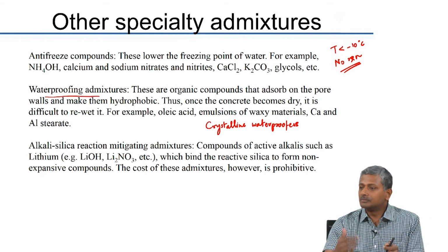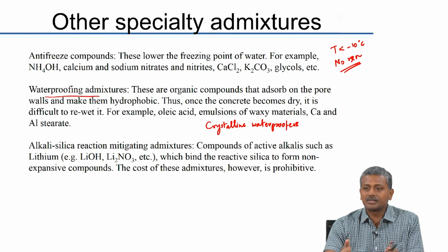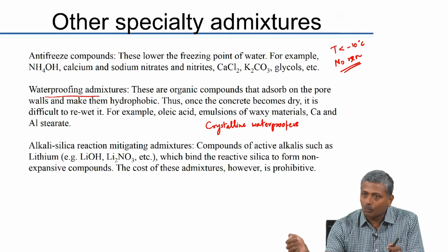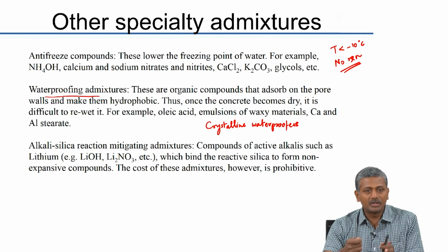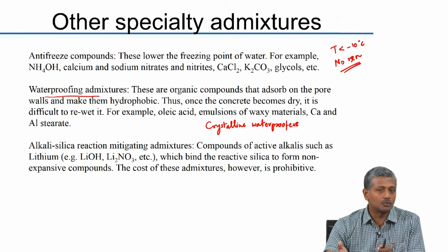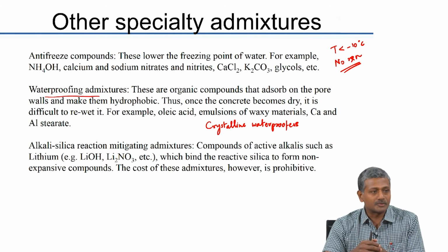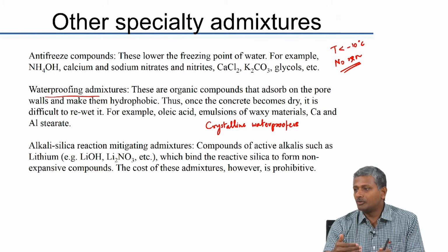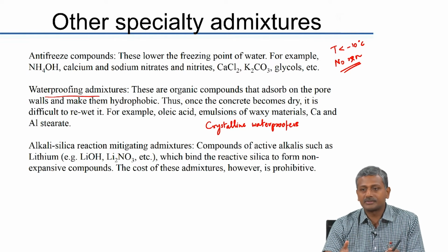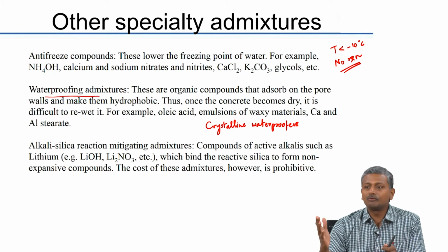Now, for the most part, when we do engineering of concrete structures, we engineer the structure in such a way that if there is going to be likely high water pressure, we provide a channel for this water to flow through, right. Good engineering practice means you provide a channel for the water to flow through. That does not mean you make your concrete porous and allow the water to come through the concrete, because then it will be a danger for your reinforcement also. You provide channels, or you provide an alternative path for the water, or you prevent completely the entry by providing an alternative flow out region.